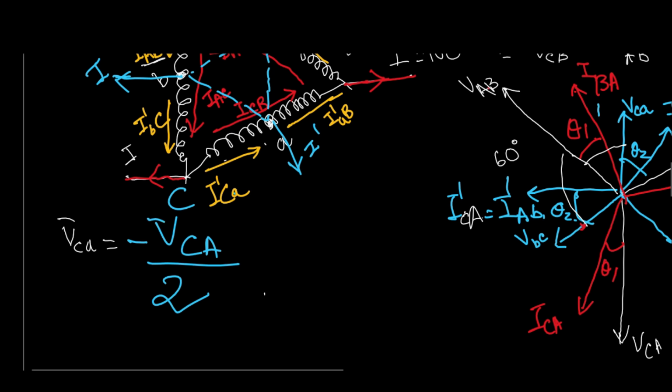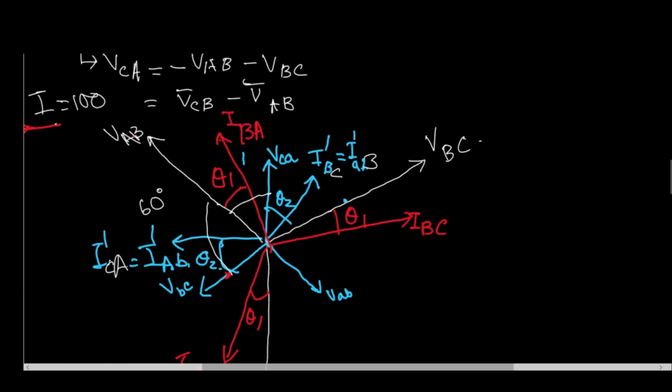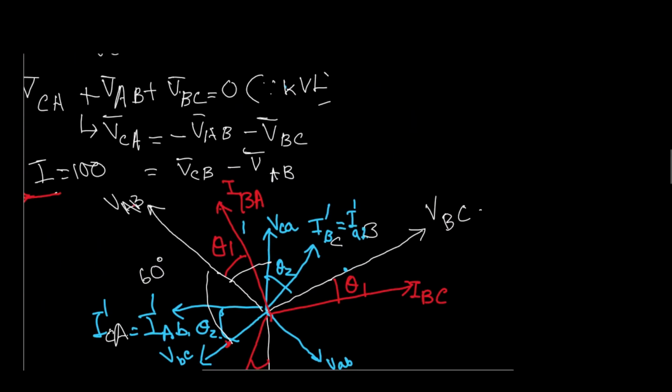So if this is the case, then based on that we have constructed this phasor diagram, right? And one more thing I mentioned: why VAB and angle IBA, we are finding this angle theta1, because in case of your source, here the transformer secondary is acting as a source. If your power factor angle is theta1, transformers or any source will view it as 180 plus theta1, right?